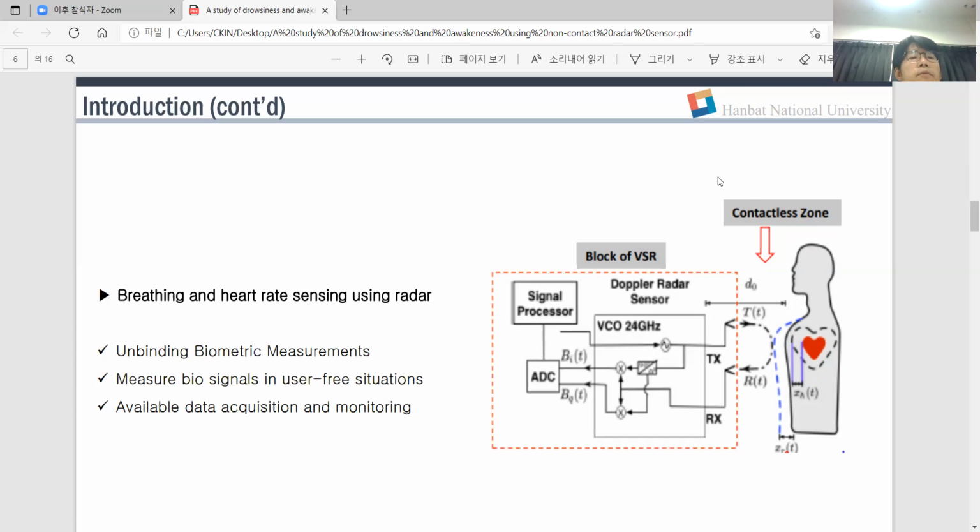In order to implement radar functions that detect various information, broadband frequency utilization, which can contain a lot of information, and transmission and reception signals of repeated pulses are required. Radar sensing technology using impulses of ultra-wide band frequency characteristics is bringing rapid technological development as digital signal processing and RF technology advanced. Therefore, the scope of radar technology is also expanding to various fields such as healthcare, defense, and living safety.